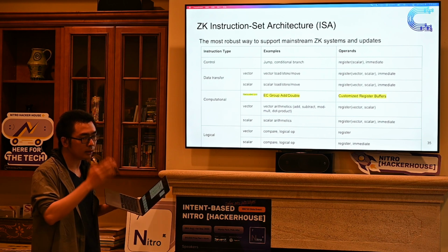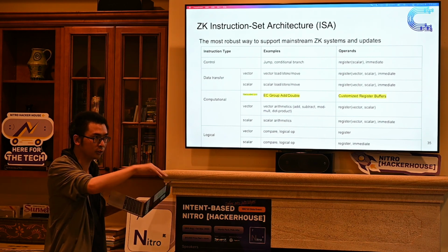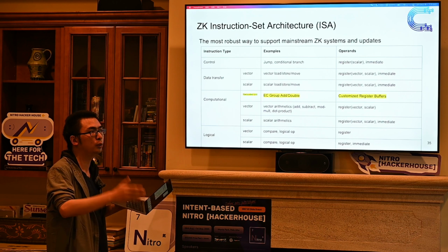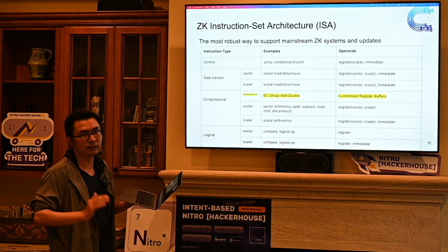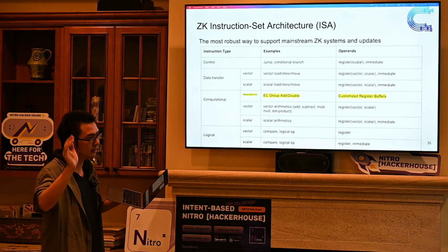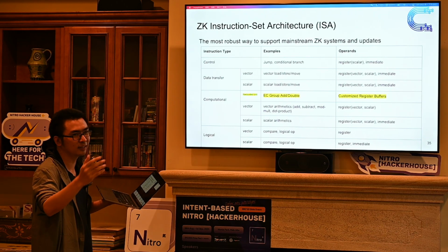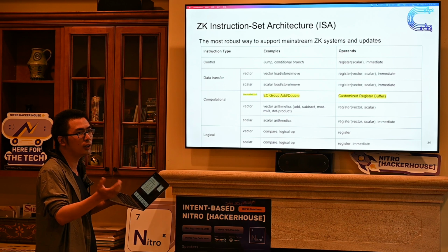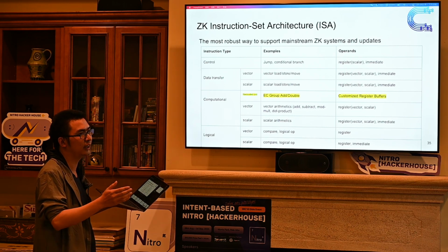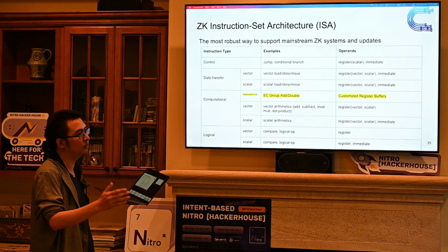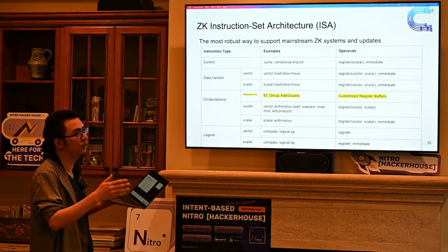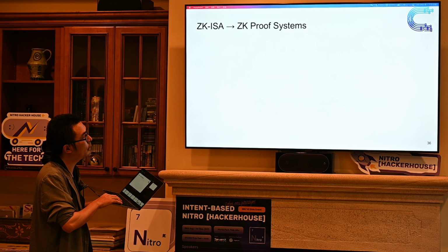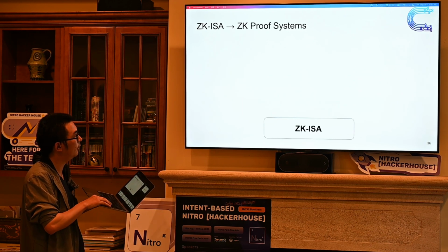hard-coded hardware units. On a CPU, if you want to offload some operations from your software, you have to go through a very complicated system stack. You have to make a system call, go to the driver, send the command through the PCIe, and the PCIe sends the data to the accelerator card, wait for the result to be ready, and then give an interrupt, and your system takes the data back. And that forces your offloading to be restricted to huge operations, each of which takes, for example, 1 GB or at least several tens of megabytes, but this one can be much more fine-grained. And this way, you can handle both fixed kernels and flexible kernels.